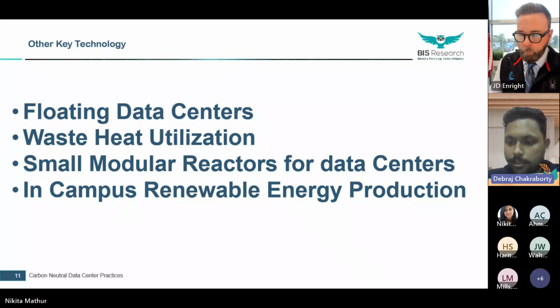Then, of course, waste heat utilization. Our Nordic friends, Nordic data centers, are using it a lot. AWS data centers in Norway and Apple data center in Norway. Apart from that, majorly data centers that are in colder climates, the heat from the process is being reutilized for district heating, especially for public buildings, swimming pools, and government offices. In some cases, there are case studies where smaller communities are also getting benefit out of it. They're calling it digital boilers, basically.